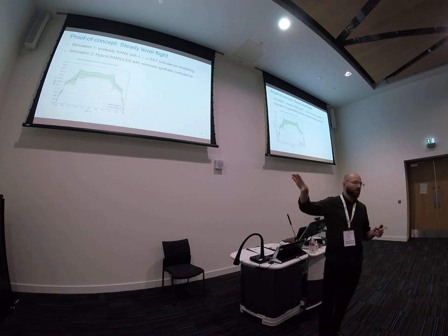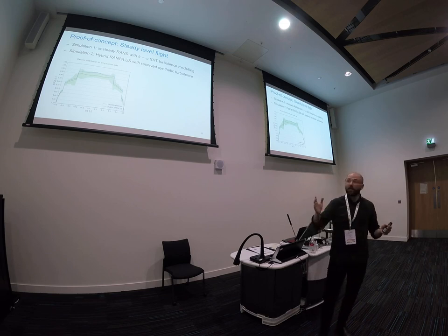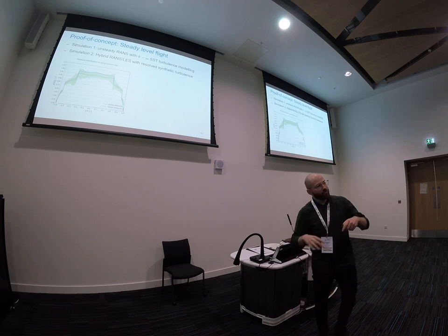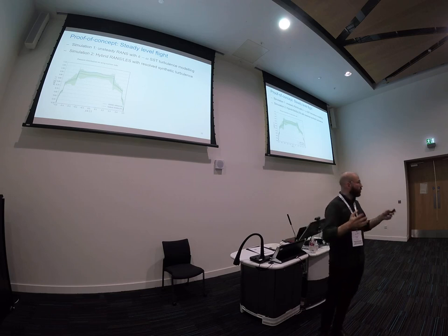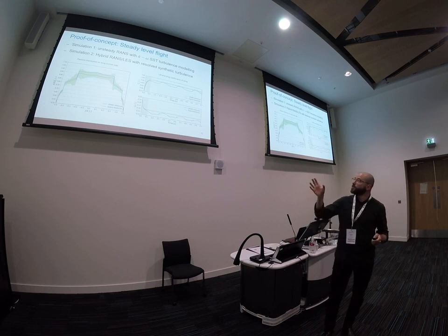So this green shaded area that you see, this is the range of, let's say, pressure forces that we have on that wing. So we can clearly see that this has quite an impact on the loading that the wing can, for instance, see. And then we look at how this integrates into more known performance metrics such as CL and CD. And we can clearly also see the effect here.